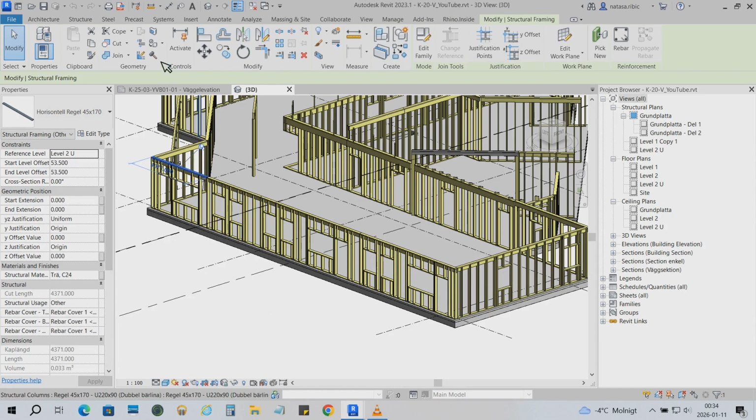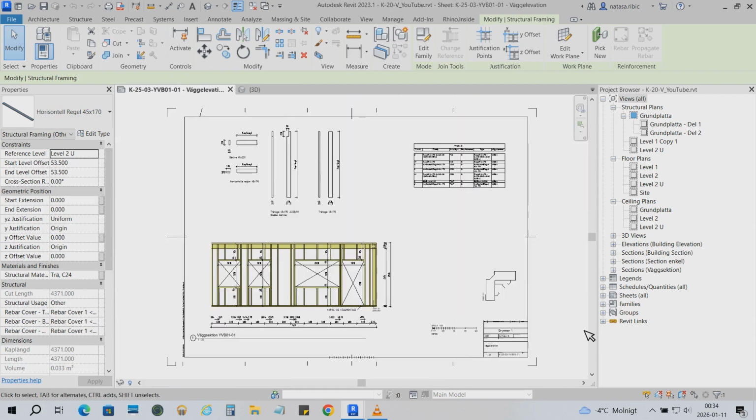I can show you the production drawing for one of the blocks. In the legend you can see that everything is built using 4 simple families. One family for the vertical joist with a notch, and we need a notch in order to place the binders, and one family is vertical joist without the notch, and those we are going to place under the windows. Then we have one family for the binders and one family for the horizontal frames. There is nothing complex here, just clear, well-defined families.